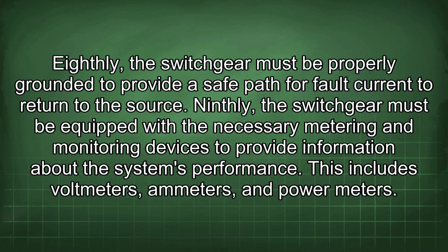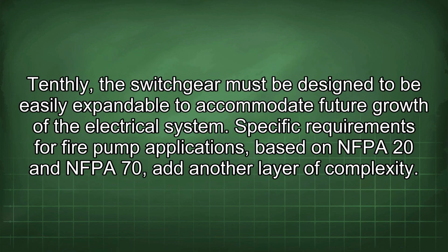Ninthly, the switchgear must be equipped with the necessary metering and monitoring devices to provide information about the system's performance. This includes voltmeters, ammeters, and power meters. Tenthly, the switchgear must be designed to be easily expandable to accommodate future growth of the electrical system. Specific requirements for fire pump applications based on NFPA 20 and NFPA 70 add another layer of complexity.